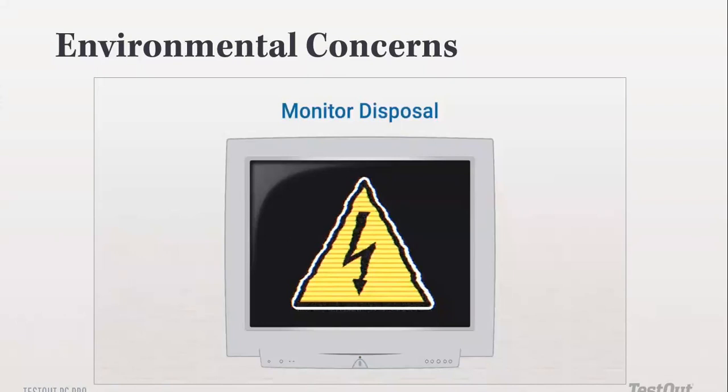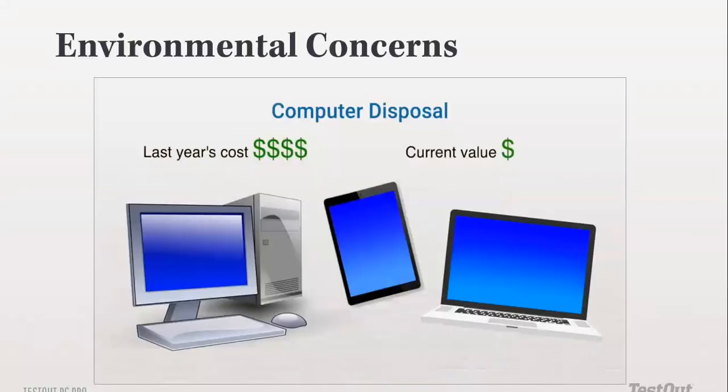If you disconnect the TV from the wall and you don't use it, just keep it there, it can keep that electricity for as long as the TV is there. So if you try opening it for maintenance, you can get a likely shock. And the electricity stored in these cathode ray tube monitors is enough to kill a person. So when disposing of them, you should send them to specialized facilities so that they can recycle them and give them new value,